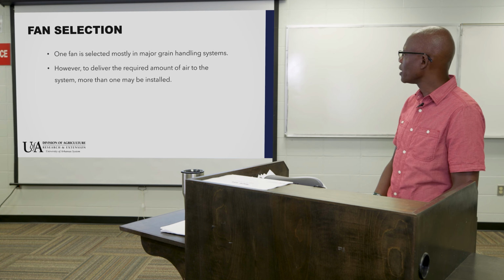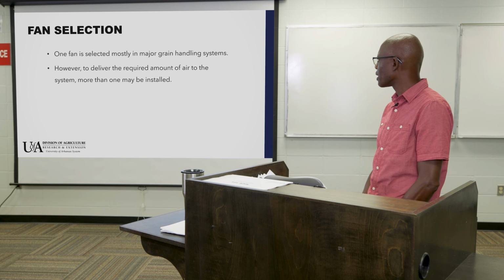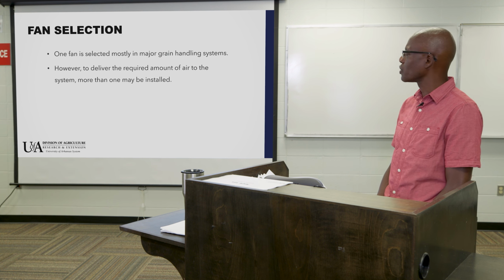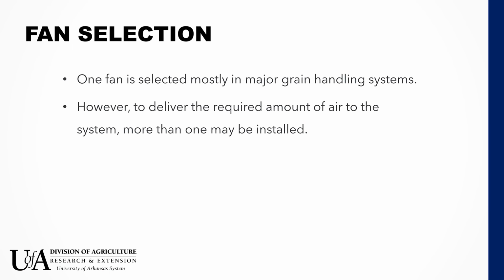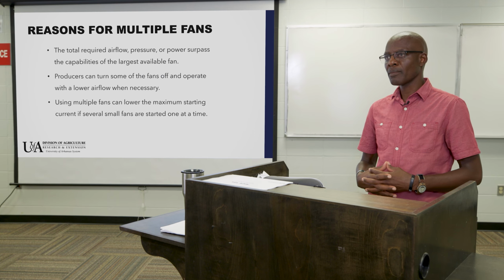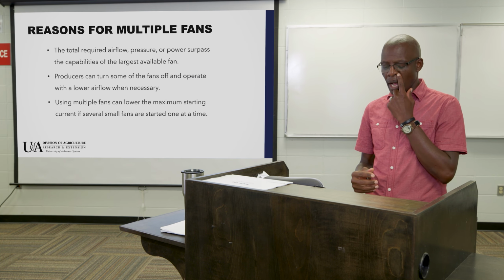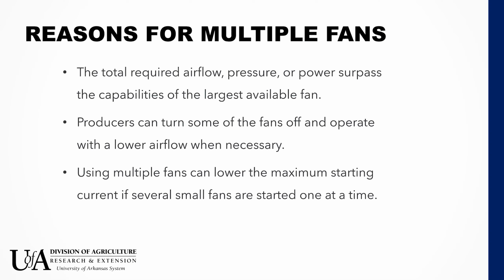Now, often we can use one fan, but there are cases where we require to use more than one fan. And in most of these cases, we need to overcome higher static pressures or to supply more volume of air. So just to summarize the reasons, the total required airflow may be high, or the pressure may be high, the power may be high, and so in those cases we need larger fans.